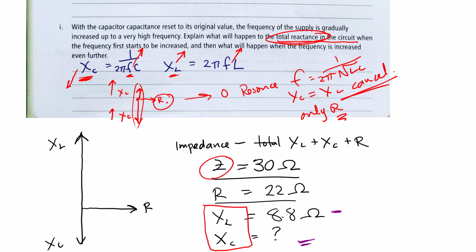And as the frequency then increases further, the inductive reactance will increase and the capacitive reactance will decrease even further. Okay, so overall the total reactance will increase as that frequency increases very greatly. Next questions are going to be on resonance.